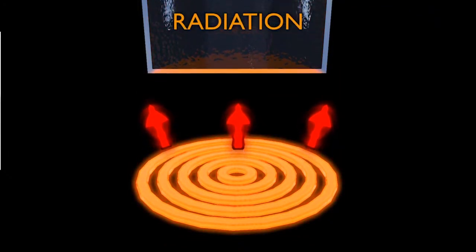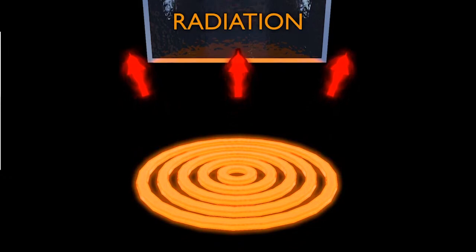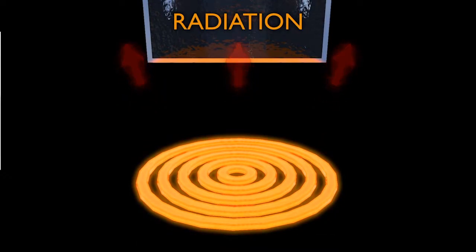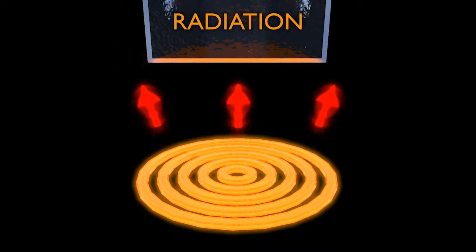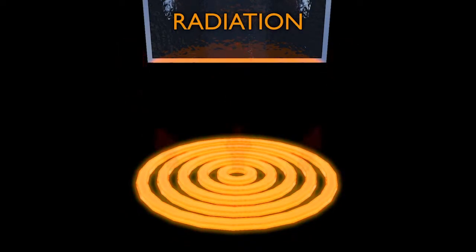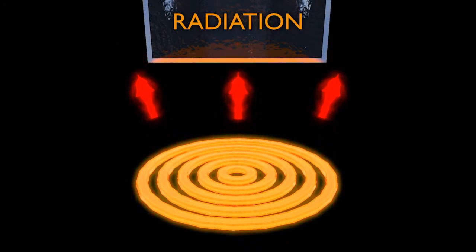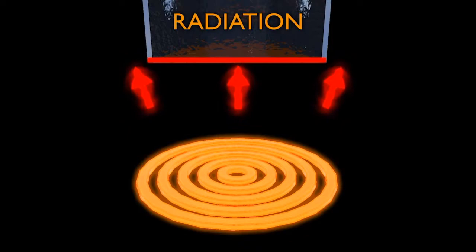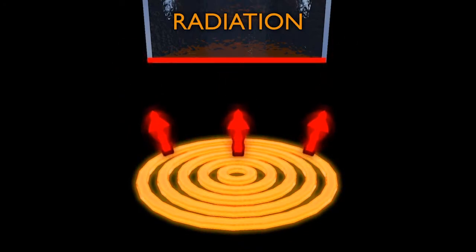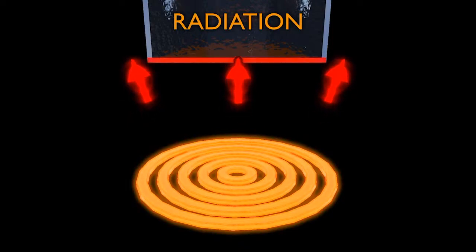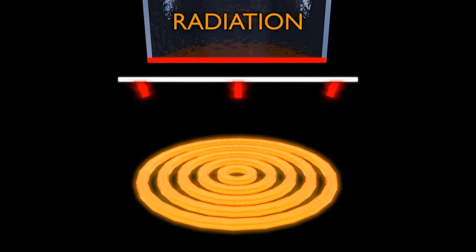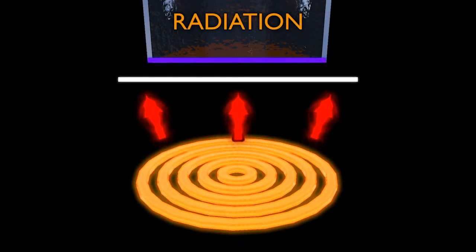Radiation. Radiation is the transfer of heat from one material to another, which occurs by means of electromagnetic waves. Radiation does not require either physical contact of the materials or a fluid medium. A warm surface such as our hot plate will emit infrared radiation, which can travel across a space, even in a vacuum. When these infrared waves strike another object, they are converted back to heat. The efficiency of this conversion process is governed by a property called surface emissivity. The lower this value, the less able a material is to absorb or emit heat via radiation. In construction, reflective foil membranes and foil-faced insulation materials can help limit heat transfer by radiation.